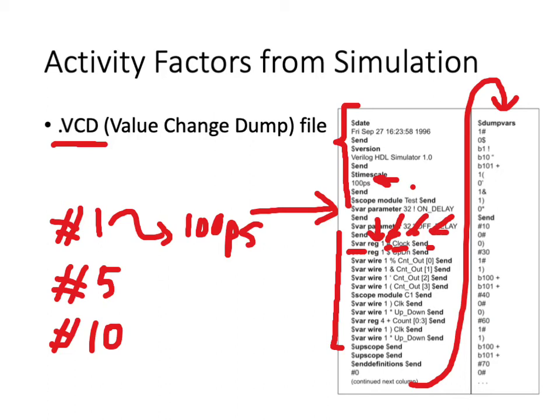If the net is actually an array, that is a bus having more than one wire, I'm sorry, this is not the initial value, this is actually the size of the net. Then this is recorded in the value here, the size of the net, and the name. You can also see the Verilog form that gives the enumeration of the array from 0 to 3.